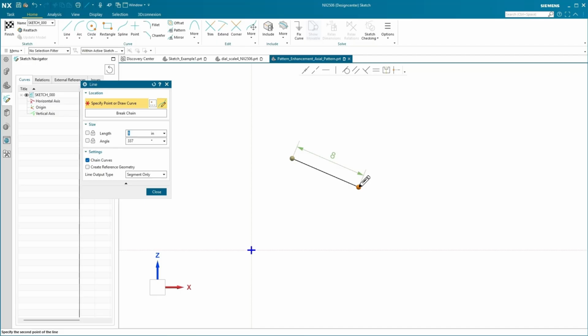That means you can currently type in a value if you want to give that a known value here. So if I type in 12, you'll see the number 12 is entered into the entry box there. I can hit the enter key now, and I can lock that value in and lock the length. You'll also note once you hit the enter key on your keyboard that the length lock box has a blue check mark next to it, and that indicates that this is now locked out.